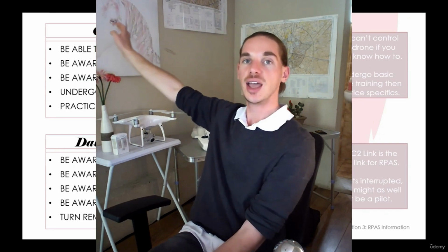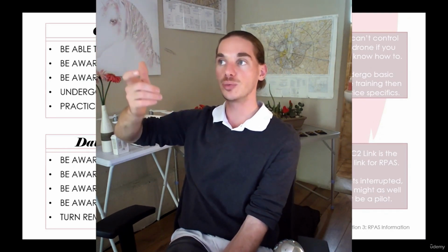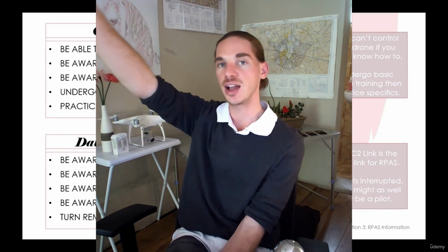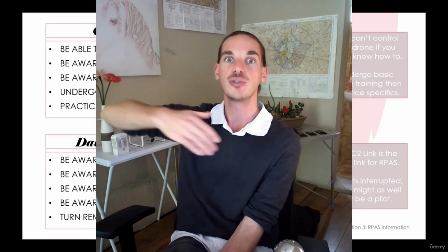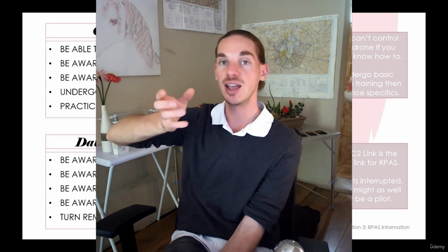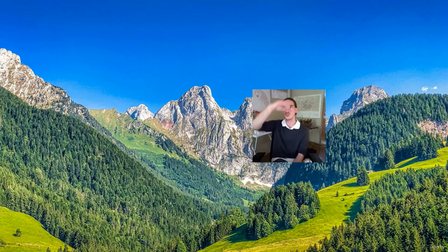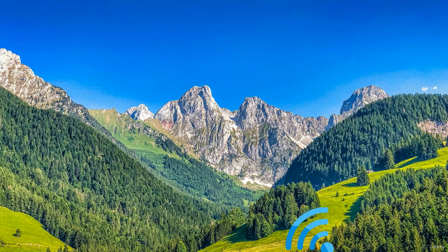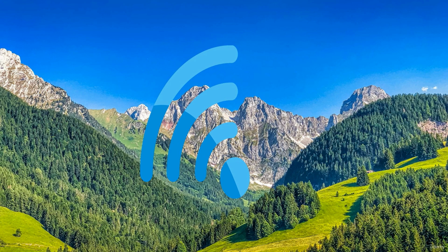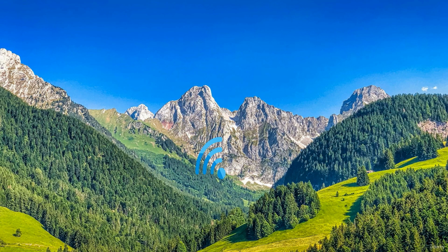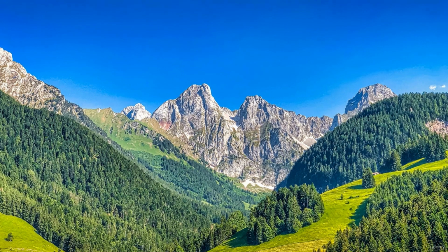You need to be aware of obstacles. Are there things in the way? If I have a perfectly open field and my remote control will reach the drone across this whole field, except in one place, just behind a tree, then of course I know there's an issue, because the radio signal is not strong enough to get through or past that tree. Landscape is important because of mountains, right? If I'm flying over and beneath a mountain, my radio signal has to go over the mountain, which means it has to extend itself, which means I need a strong radio signal. Otherwise, generally, it's going to try to cut through the mountain and come to a dead end or halfway. It's not going to get through the mountain.